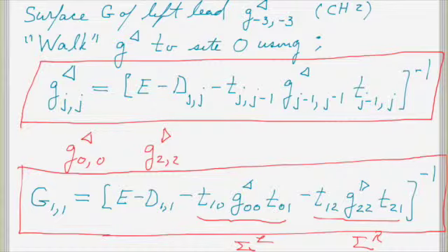And the left connected at 0, 0 includes everything from 0, 0 back to negative infinity, whatever band bending is going on there. So they are surface Green's functions because they are at terminated surfaces, but they're not of some ideal crystal, because they include the effect of all the band bending to the left and right of them.